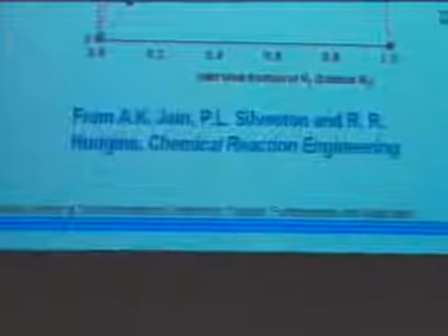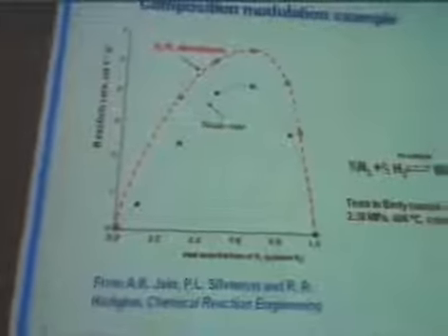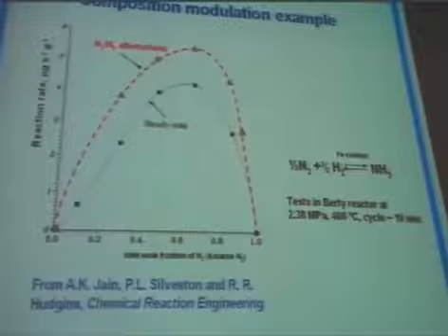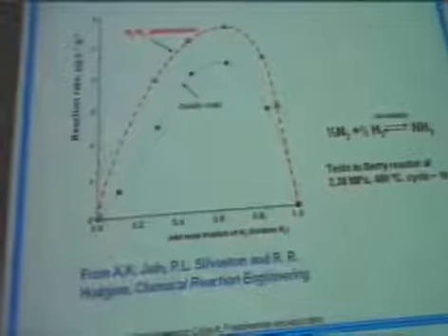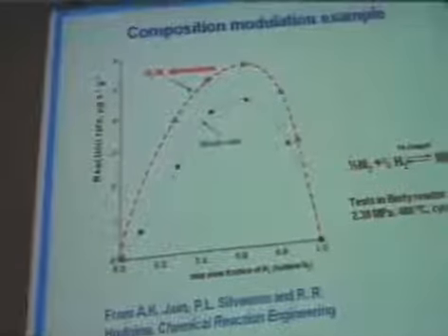Another example. If I periodically change the ratio between hydrogen and nitrogen for the catalyst in the synthesis of ammonia, in this oscillating case, I can achieve a situation when the rate of creating ammonia is higher in comparison with the same conditions in the steady state case. There are a lot of publications showing the increased efficiency of processes when the inlet concentration is oscillating. Only Professor Sylvester with his team published, I think, maybe 300 publications for different processes, and in every case he showed excellent results.